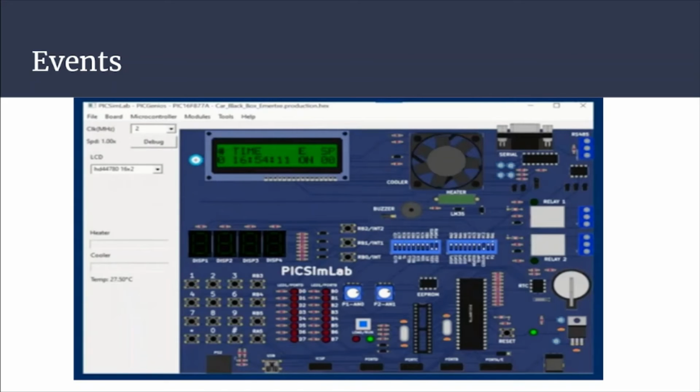Set time should show the current time. The seconds field should blink indicating the field to be changed. The up key should be used to increment the time. Rollover on reaching max. The down key will be used to choose the field. And a long press of up key should take you back to main menu.